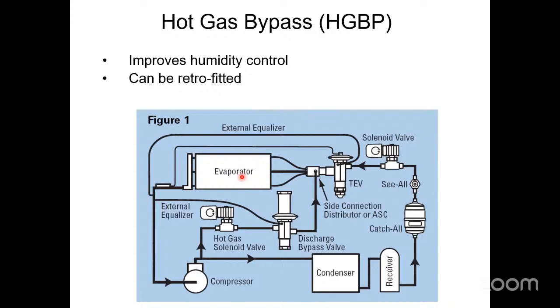It's not great. And anytime you say the word bypass, it pretty much means energy waste. It's like driving your car with the gas pedal all the way down and the brake pedal halfway down. Like, yeah, you're going the speed you want, but is there a better way to do this? Probably there is. But you can do this to get capacity control. As mentioned, energy code restricts this because obviously it's not energy efficient to run the compressor balls out and then try to throttle it back by falsely loading the evaporator. So energy codes prohibit this, but you are allowed to use it in limited fashion.